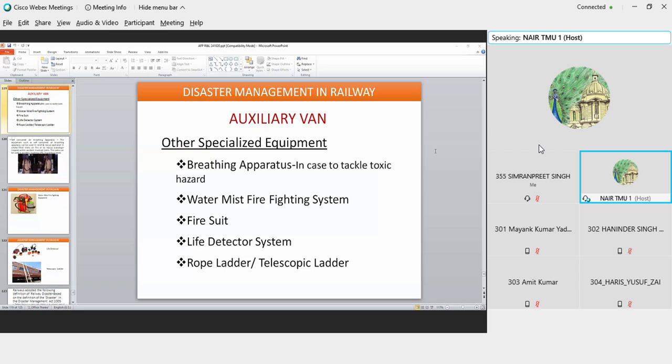You see what happens, assuming you are doing a right hand curve. Now in the right hand curve, the flange would have such a location where the frontal portion of the flange starts biting onto the rail, and it will have a tendency to mount the rail. So that is called positive angularity of attack, and it assists the derailment process.